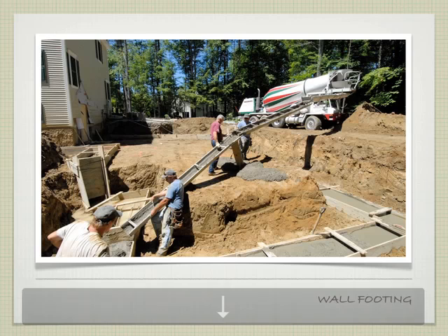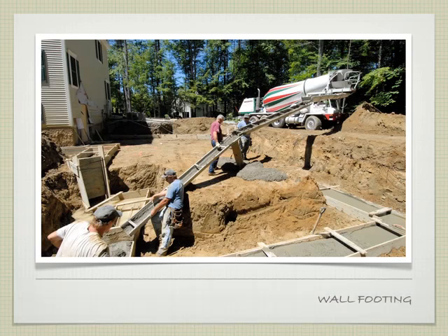So if we were actually pouring this kind of footing, it would look something like this. And we'll see a bunch more of these examples when we get a little further down the road in concrete. Since we've been talking about dewatering, I'd like to point out how much water is in here, which is a concern if I were doing this building, because this water can tend to separate out the concrete, which gives you a lesser strength of concrete and could compromise the foundation long term.